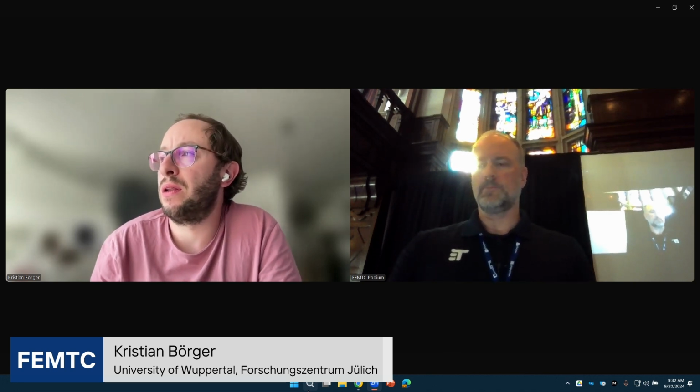I wouldn't say in that work, but in our previous work, we also did experimental work, not on smoke detection, but on measuring spatially and temporally resolved extinction coefficients. We developed a photometric measurement approach for that with consumer cameras that you put in an experimental hall, and then have a layer model where we can backwards calculate extinction coefficients. So maybe that's something similar to what you were talking about, but it's not directly related to this work. This is more on the application side and performance-based design.